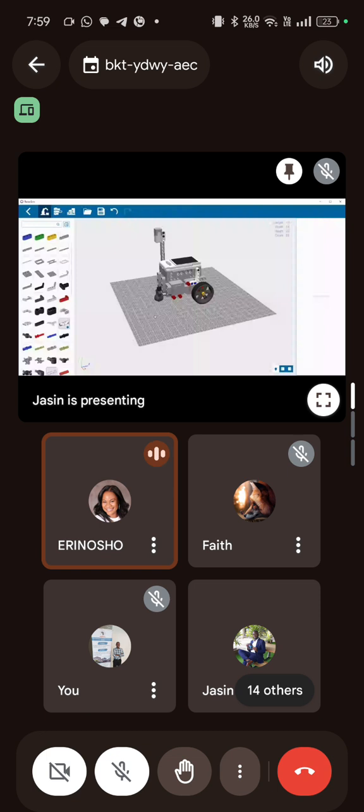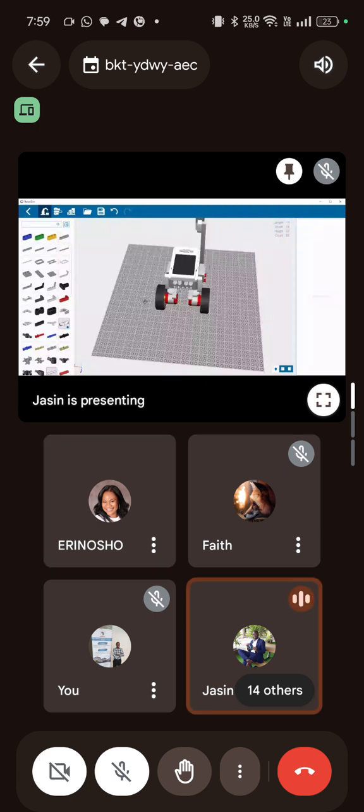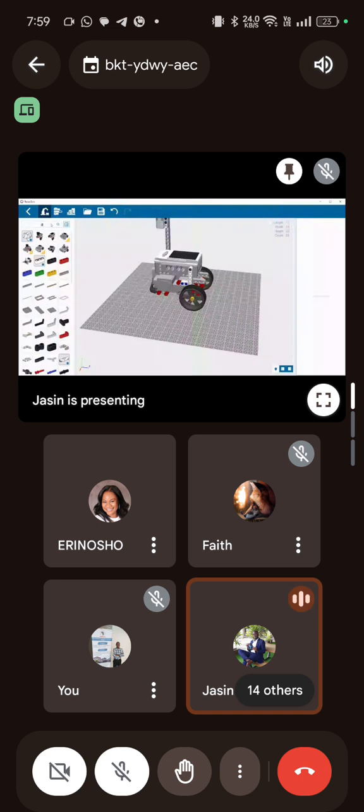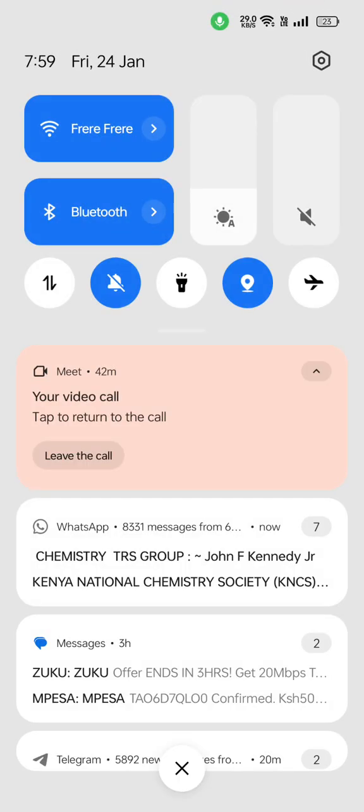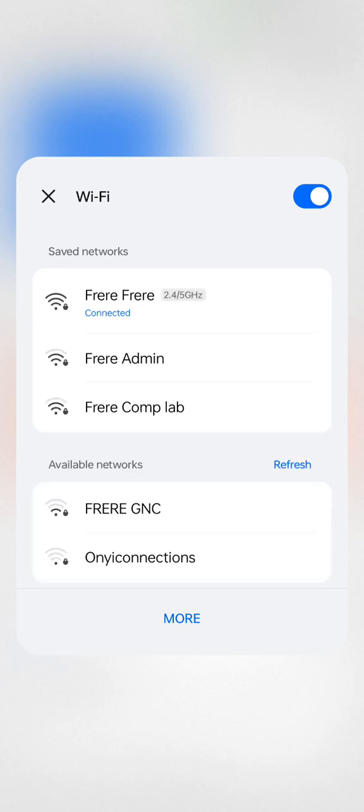Okay, so I succeeded in changing the orientation, but the pins, where did you get the pins that you put in the holes before putting the pins? Oh, okay. Yes, the pins are here. So there's a search bar. You can always search pins or connectors. Or alternatively, besides the search icon, there is another icon that looks like a book. So you can click it, and then you have a library of pins to select from.